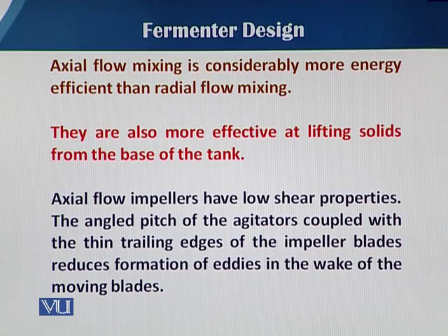The axial flow impellers are mostly designed to decrease energy consumption, and they are used when less shear effect is needed. When there are sensitive conditions where no shear effect is required, then we mostly use the axial flow impellers. They are also more effective at lifting the solids from the base of the tank.